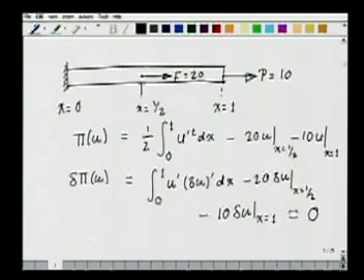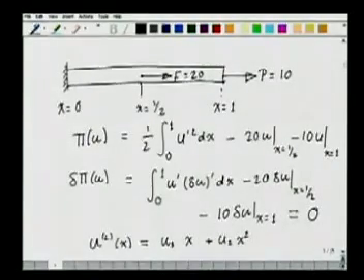Again, if I take a 2-term solution as an approximation to the u of the problem, so u2(x), as we had done for the previous case, is equal to u1 x plus u2 x squared. So again we go through the same steps as we had followed for the previous problem, and we can obtain the coefficients u1 and u2 of the approximate solution that we have obtained.